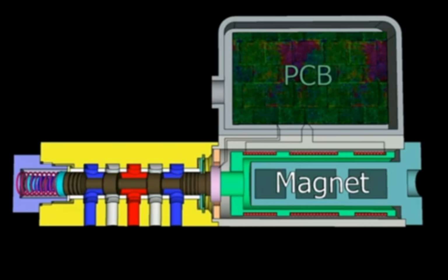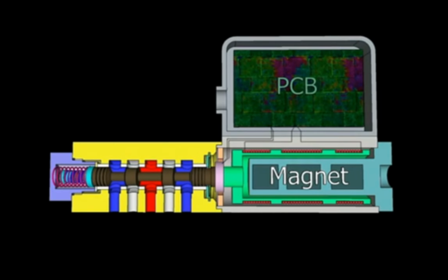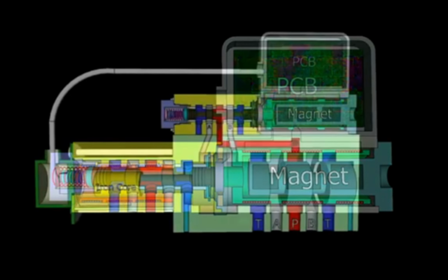At the end of the pilot valve there is a self-centering spring, which fails safe: whenever the power is switched off, the spool will come to the center. And this pilot valve is fitted on the main spool valve, which actually allows the high pressure oil to the fuel oil pressure booster.